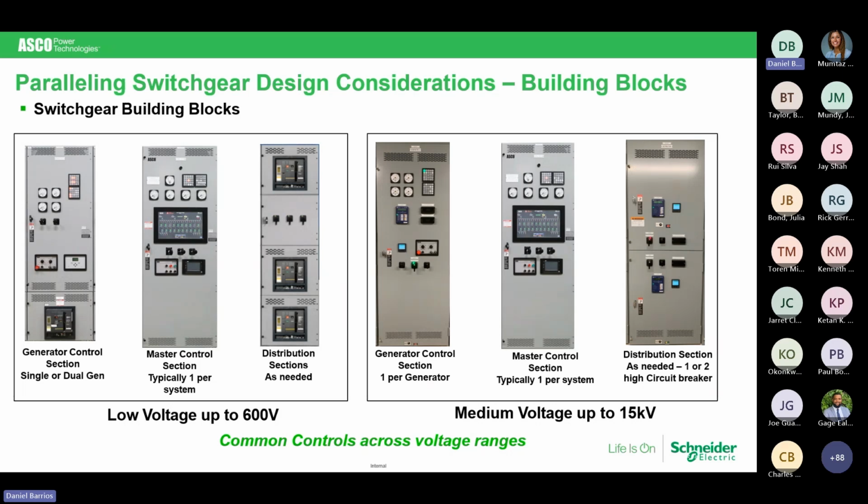The distribution, when you are explaining to me what you want in your system and how you want it to operate, please let me know if those are manually operated breakers or if you need those electrically operated. Well, why do we need to know that? As you can see in this photograph here, one of the sections of that 4-high cubicle cannot be used with breakers because that's where the controls go into. Just an item to work out with Mumtaz as you're putting your project together.